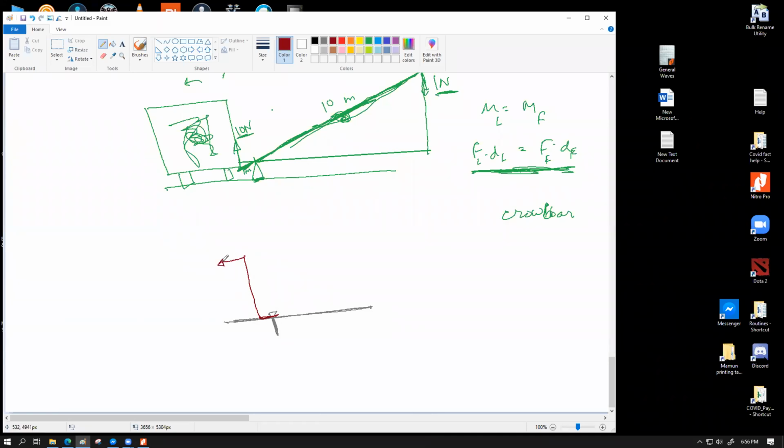So this is a horizontal force. Using this corner of the crowbar as a contact point of pivot, this end is going to start pulling this up. So you can see over here, for this figure, both the forces were vertical. This was being pulled downwards, this was being pushed upwards. But over here, this is also working as a lever, but because the lever is 90 degree rotated in its structure, applying a horizontal force gives an output of vertical force.